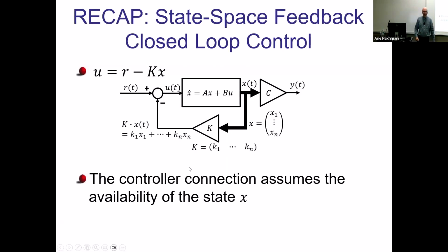Yes, just to remind you what we learned previous time, we talked about state space and how to design a controller for state space representations of the system. And we described three different methods, including comparison of coefficients, Bass-Gura formula, and Ackermann's formula to design that controller for state space. The controller is just a vector of numbers which is connected to state X, and then you return the dot product Kx back with negative feedback.